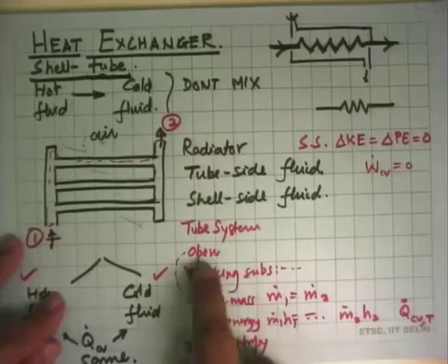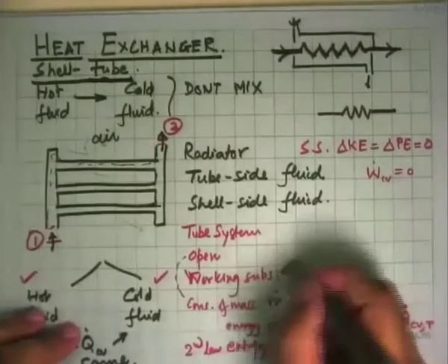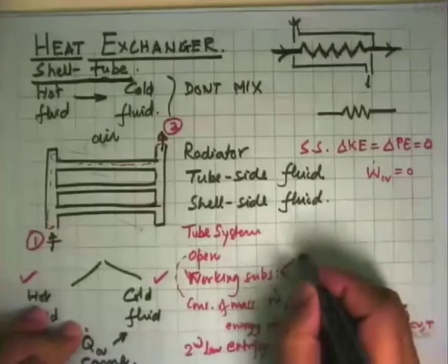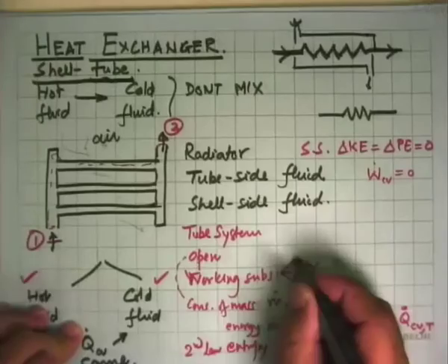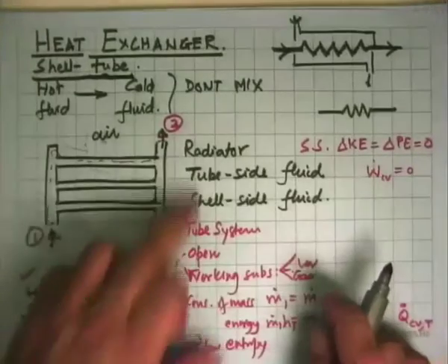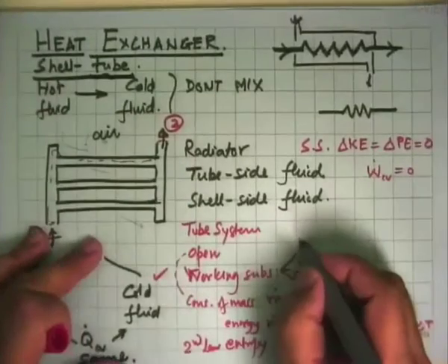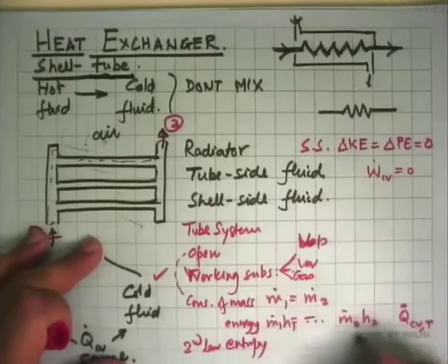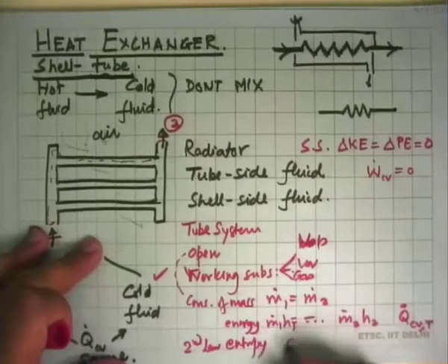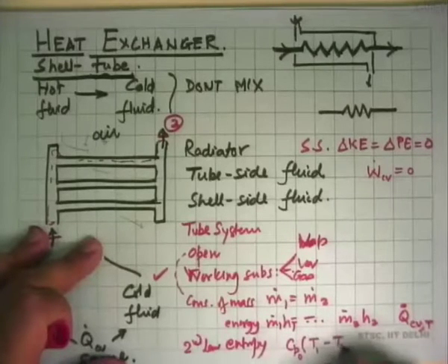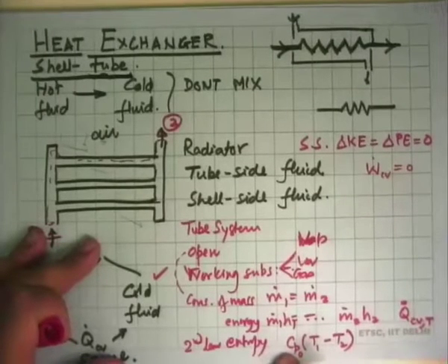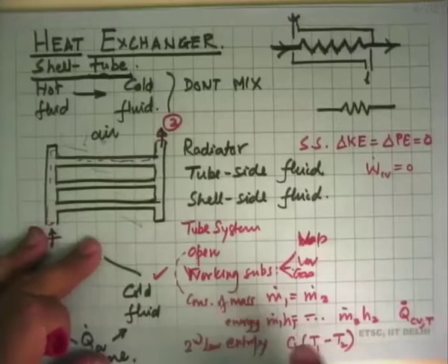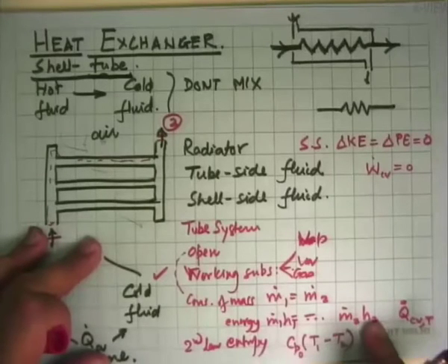Then depending on the substance that we had, if it was a vapor or a liquid, we deal with it in one way. If it is a gas, it's something else. Even for a liquid, if we know throughout the system there is a liquid, like say water going through it, then in both cases we will write the difference of enthalpy as Cp or Cp0 times T1 minus T2 or T2 minus T1, whichever way that is. So we only need the constant pressure specific heat of the material. If there is a phase change, we cannot do this.